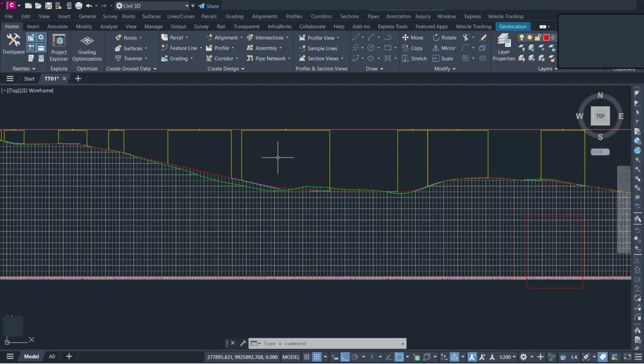You have the bed of 50, you have a ring of 150, you have the culvert of 900, and then you have another 150 here. And then on top of that, there is something we call minimum cover, which should be 0.6 meters for any culvert, whether submerged or emerged or whatever it is.